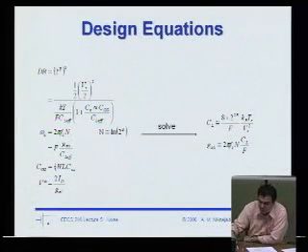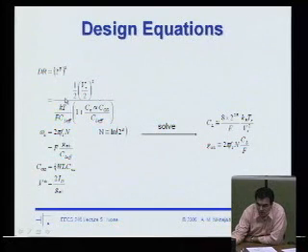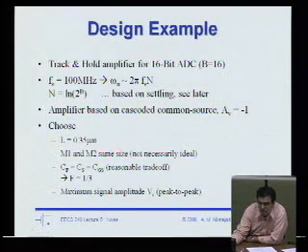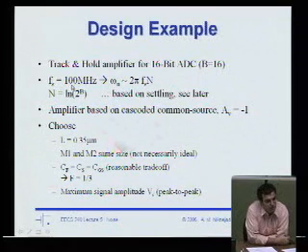So the dynamic range of the circuit is, of course, the voltage swing. Let's assume that it's Vs over 2, kT over C times this factor F times 1 plus this extra noise factor. And if you actually solve these equations, basically you're just using the assumption that, so I should have stated where this assumption of omega u comes from. We're assuming that we're going to sample the circuit at 100 megahertz.